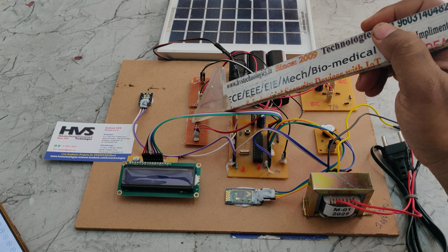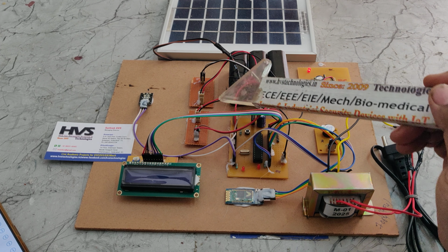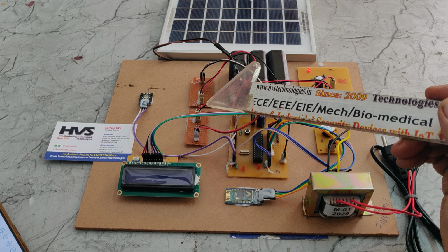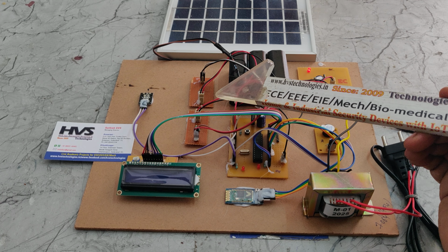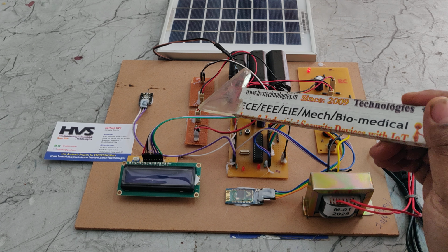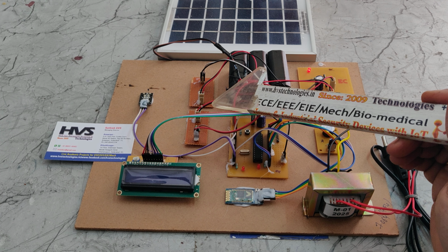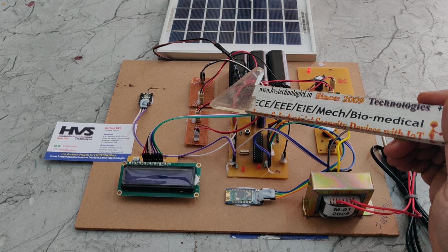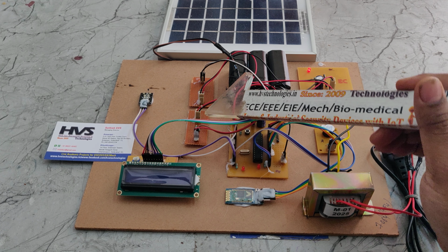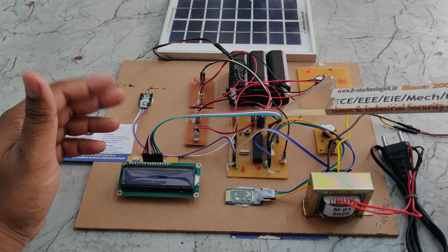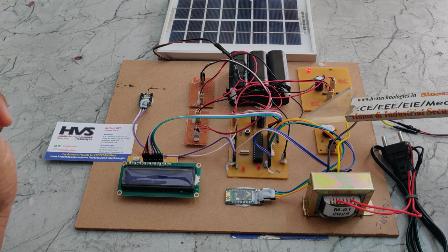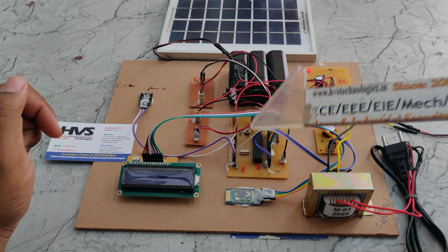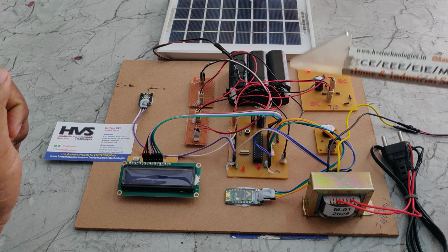These 2 sensors look the same, and they have a 10:1 potential divider ratio with the help of resistors. We are using 10 kilo ohm and 1 kilo ohm resistors, 2 resistors for input, and we measure the output voltage across the 1 kilo ohm resistor, so that we get the 10:1 voltage ratio. When we provide 12 volts input to this voltage sensor, the output is 1.2 volts. In the microcontroller we programmed it to multiply that by 10.